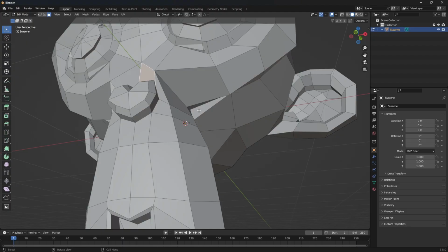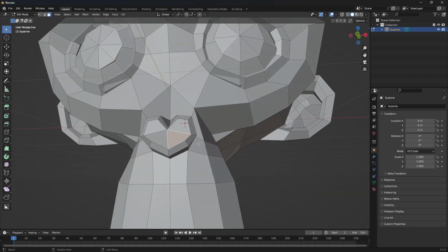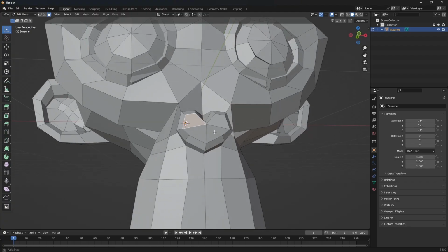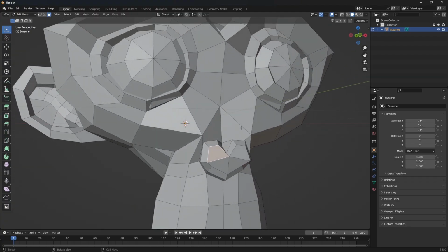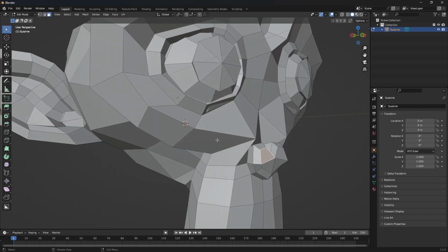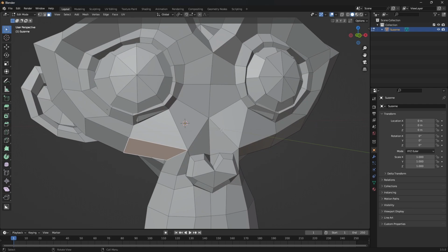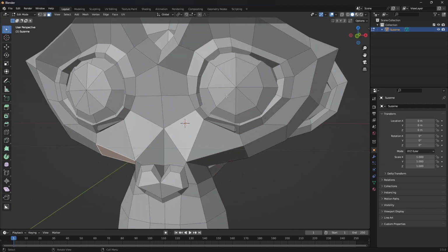So there, you're going to have the occasional triangle, but most everything here, even in a complex shape, is going to be a quad because it just is going to render much better. It's going to print much better. You certainly don't want more than 4 vertices. If you do, take that face, split it into parts so you have a quad and 2 quads, or a quad and a triangle.